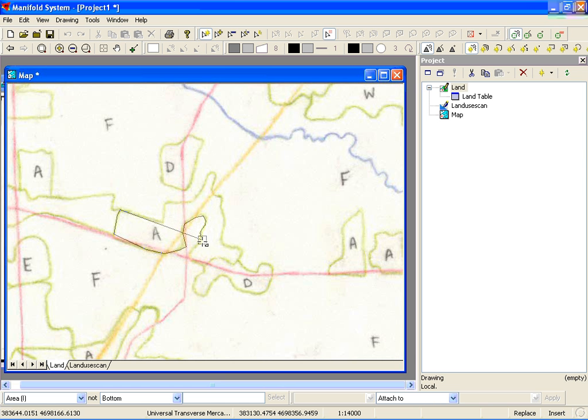Now I'm going to skip ahead in the video so it doesn't take so long, but you can, again, spend some time digitizing the data yourself. So any jumpiness you'll see is just because I skipped ahead. If you right-click, that will close off the polygon. So a right mouse button will actually end the polygon that you drew.